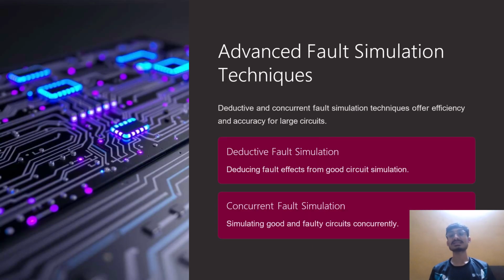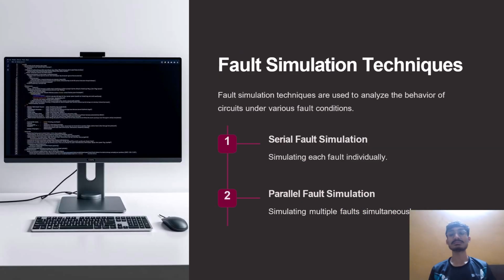Advanced fault simulation techniques. Deductive and concurrent fault simulation techniques offer efficiency and accuracy for large circuits. Deductive fault simulation deduces fault effects from good circuit simulation, and concurrent fault simulation simulates good and faulty circuits concurrently.